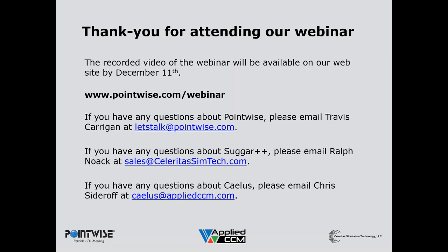So in terms of overall effort and time, and this is a bit arbitrary, just a rough rule of thumb for something complex: if multi-block structured mesh took 100 units of mesh generation time and the unstructured meshing approach took 1 unit, then maybe the overset is 10 or something like that.